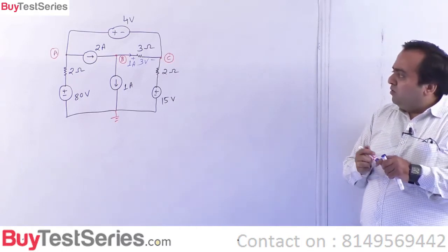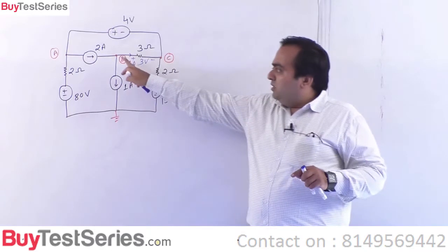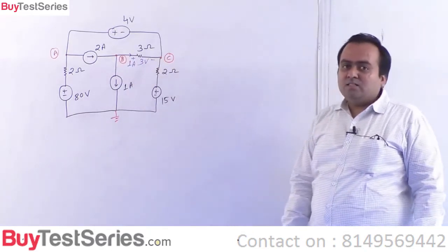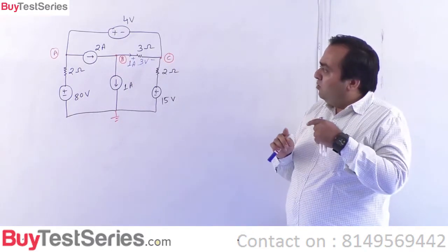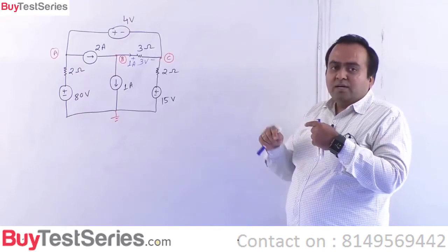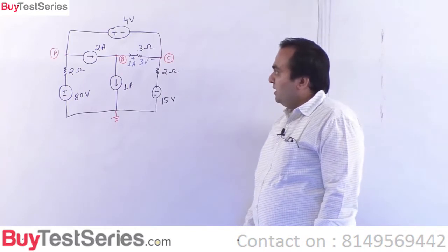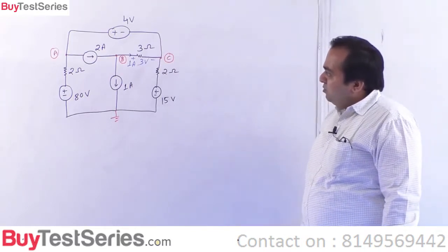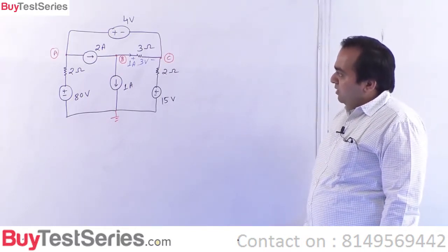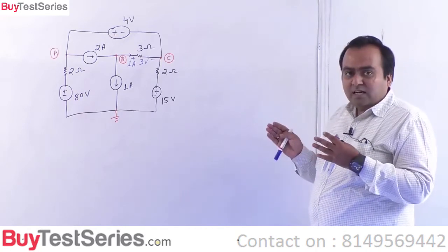Alright, these are the information that we get to know once we look at the circuit. So the currents are balanced at this B: the 2 ampere goes into it and 1 plus 1, 2 comes out from it. Is this okay? Now we have to find out other branch currents.